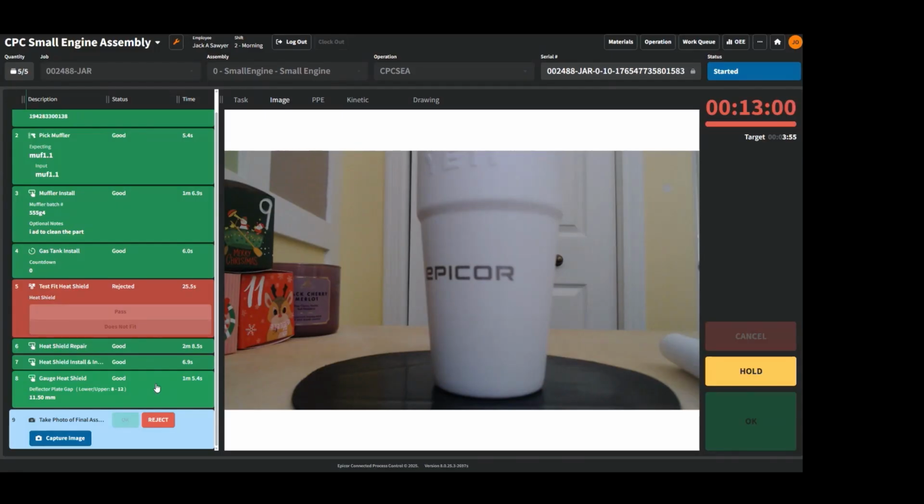Or what if you're taking images along the way because you build a multi-layered unit, and housings and everything else go on? If it gets down to testing and it fails, you don't have to take the whole part apart in different operations. Instead, you could be visualizing these images. There's a lot you can catch in an image. Maybe wiring is done incomplete, or the wrong harness, or soldering.